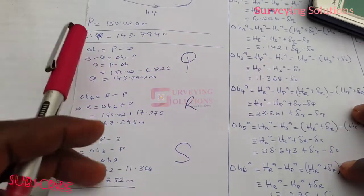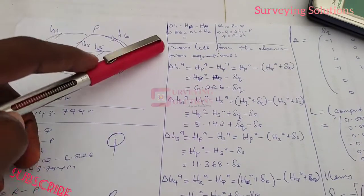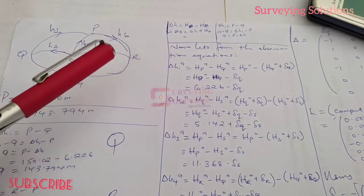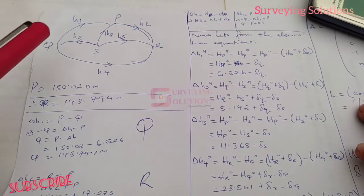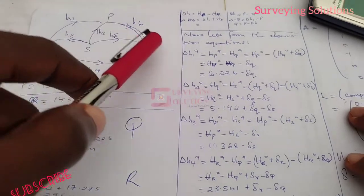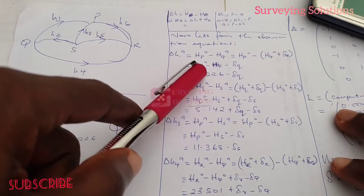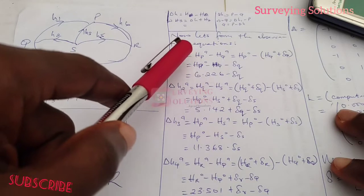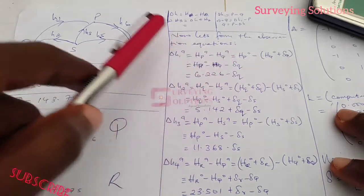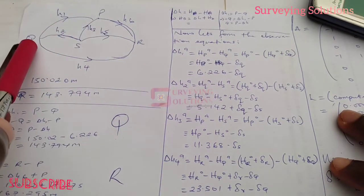Good. So now, as we have gotten the observed heights, or the provisional heights, of the 3 points, we can now move to start forming the observation equations, right? Let's now form the observation equations. The idea of forming the observation equations is still very simple from what we have explained earlier. If you look very closely, you would see the directions as we have talked about. Now let's say change in h1. The formula still goes as change in h1 adjusted is equal to the height of P adjusted minus the height of Q adjusted.